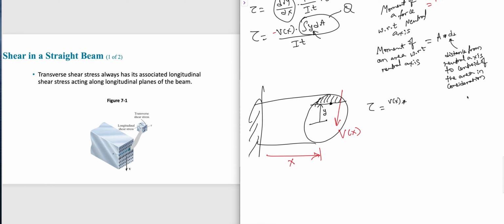And why did we take this area? Because I asked you what is the shear stress at the point. You had to take the area above that point till the top edge. So you had to take all this area.